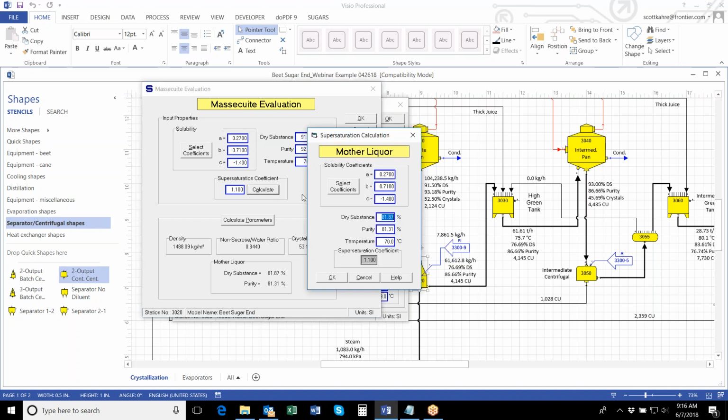But if you don't, you can click calculate and enter the parameters of the mother liquor. And this is where what Jeff's talking about comes in. If you have, we call it a Nutsche press or a Fillmass press. Basically, it's just a little device that uses air pressure to squeeze fill mass and push a sample of mother liquor out.